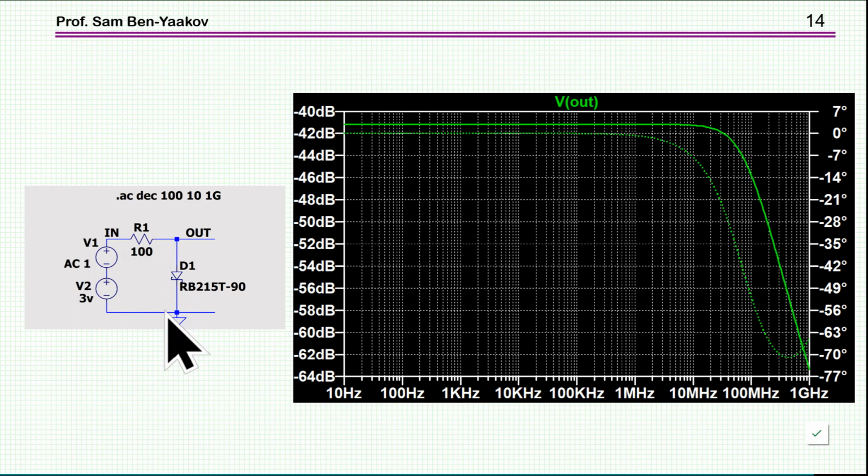And at the operating point, it will extract the small signal model or equivalent circuit for the diode, and then it will run a phasor analysis. And here is, for example, V out, in this case, for say 3 volt bias. We are pretty high on the curve of the diode, and again AC analysis. Now, what will happen if I put here a higher voltage, like 1 kilovolt? Nothing. It'll be the same thing, except that the magnitude here will be 1,000 times larger, and the current will be 1,000 times larger, because it's a linear circuit after linearization.